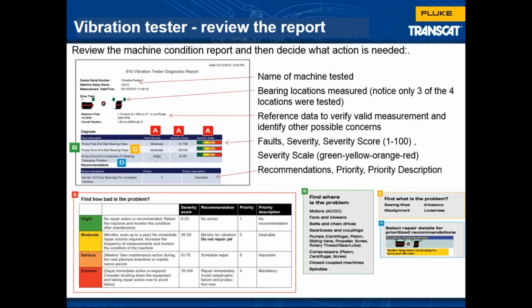An automated diagnostic system is very, very good, but it's not a black box. And if you take wrong data, you're going to get bad results. So we're going to teach you how to review the results and how to review the report, because that's the job of the maintenance technician: to give it good information, take good measurements, and then review the results before you approve the work order and go out and do the work.